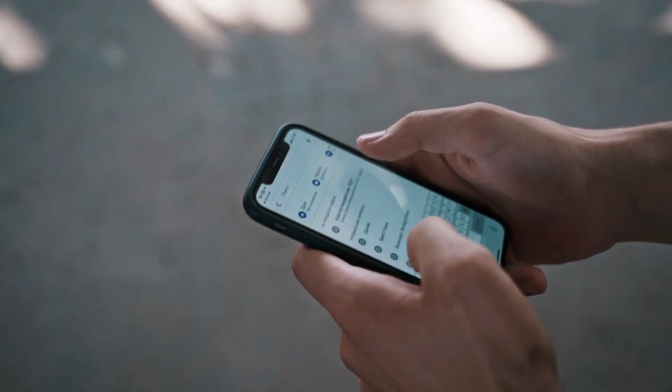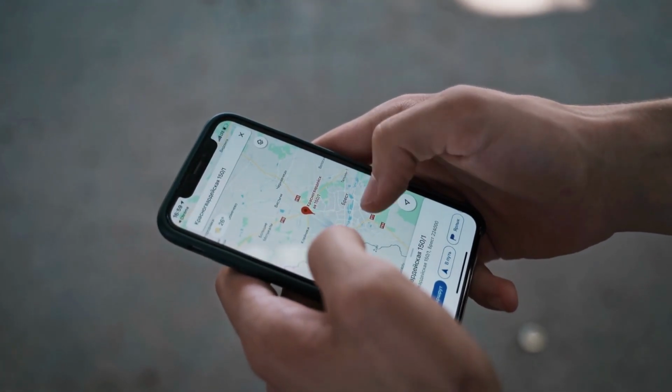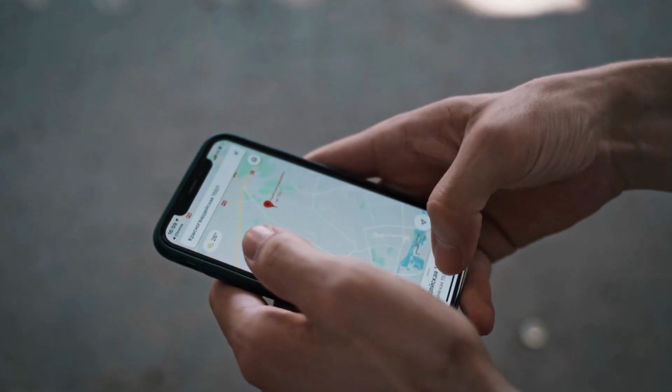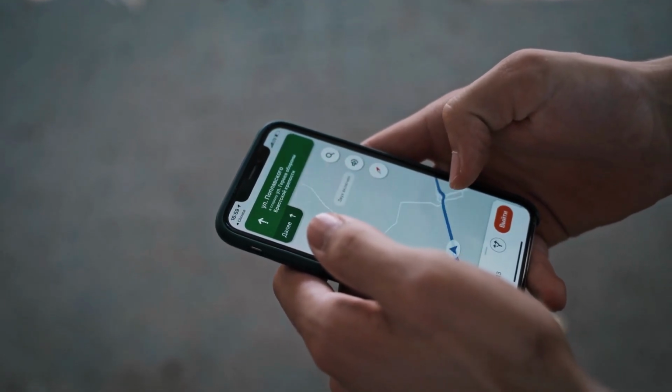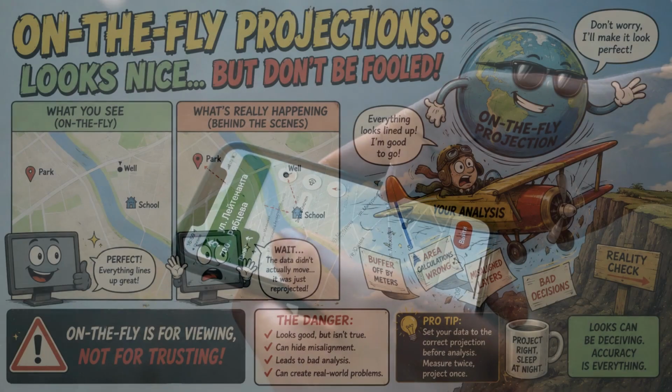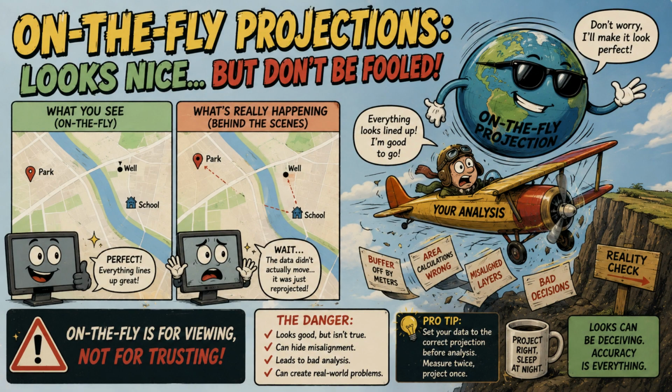This is perhaps the most crucial takeaway for your entire career. Modern GIS software is incredibly powerful, but it will trick you. How so? When you load datasets with different datums or projections, the software will often execute a projection on the fly, so the layers visually line up on your screen. But a visual alignment on a monitor is not a mathematical datum transformation. Exactly. The software might make the map look seamless, but the underlying data matrices are still sitting in two totally different geodetic realities.